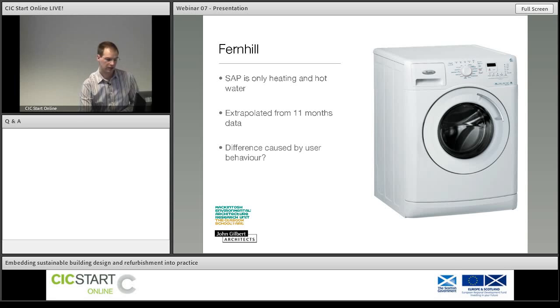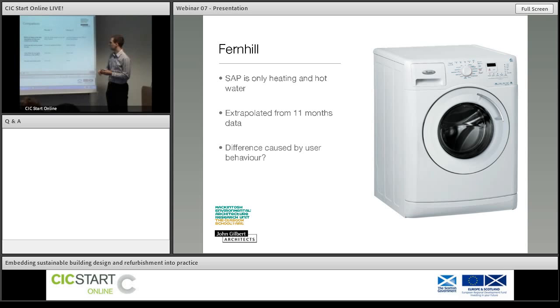And again, this is really not to go into this in a lot of detail, but you can see from these two survey results that there's actually quite a dramatic difference between the way that each house uses their heating system and their ventilation. It's a hypothesis that the house that used more energy has got its heating system on longer and opens its windows for ventilation, which came out of the questionnaire a lot more often than the house that uses less energy.